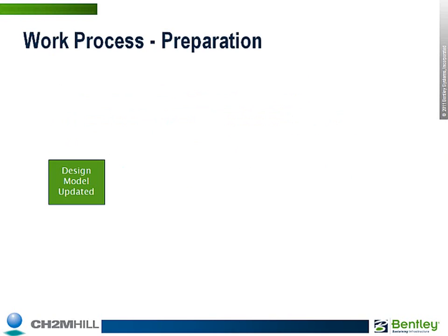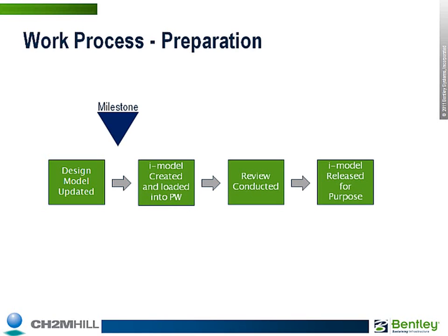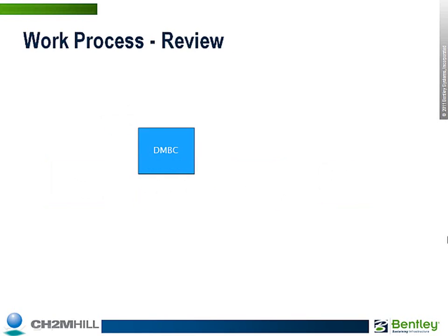Here is the workflow. Design work commences in the model until a specific milestone is reached, at which point an iModel is generated and loaded into ProjectWise. After a review is conducted, the iModel becomes the baseline for comparative purposes. At the next review milestone, the DMBC tool can be incorporated.